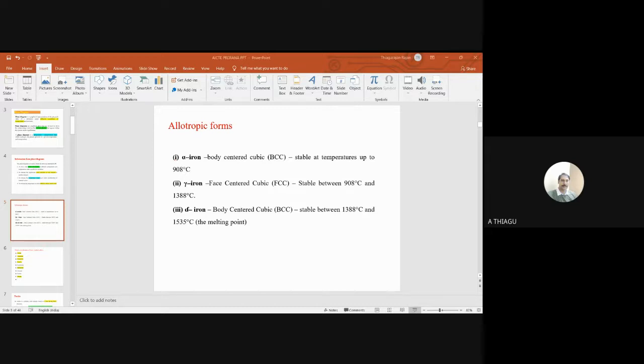That is very essential. Anyway, I will show the picture. You will be able to understand how the microstructure changes from the austenite state to martensite. The martensite structure is like needle-like structures, sharp needles produced because of the rapid cooling process.